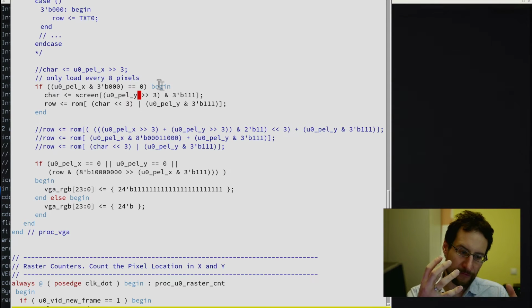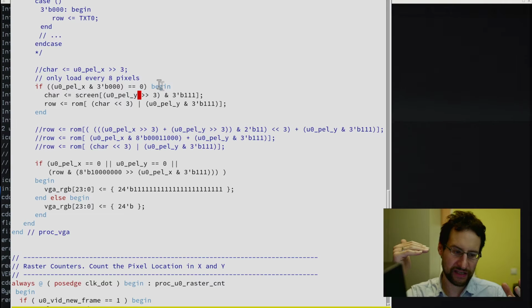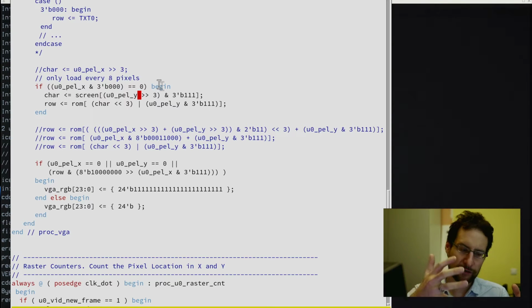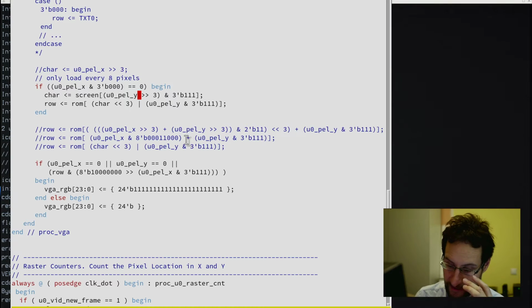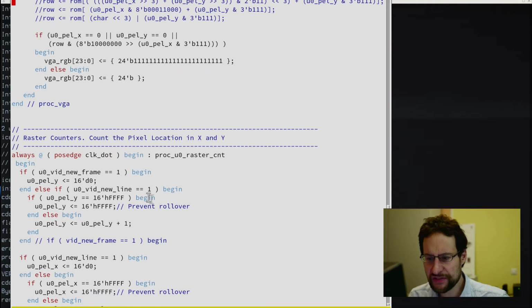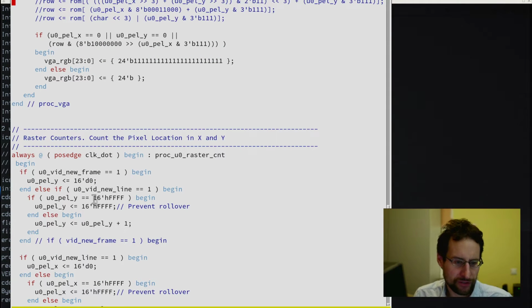Then when we load this for each x pixel, the output signals are not stable enough in the clock output, when clocking this out to the HDMI transmitter. I need to get more into Verilog again, and maybe this could be changed with this edge of this clock, because at each pixel clock we also compute the X and Y position.